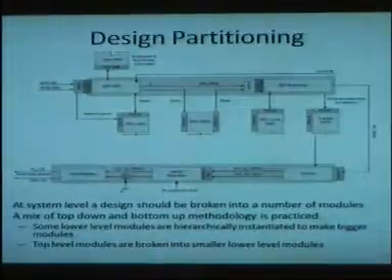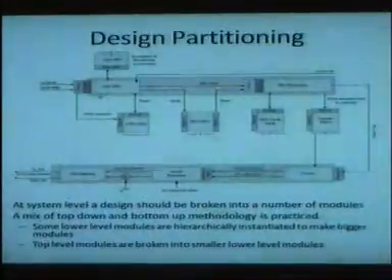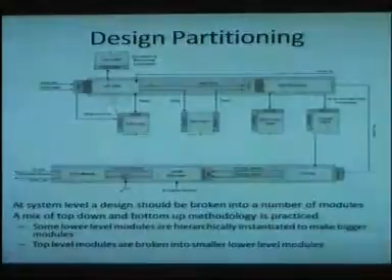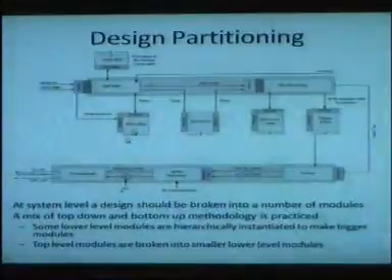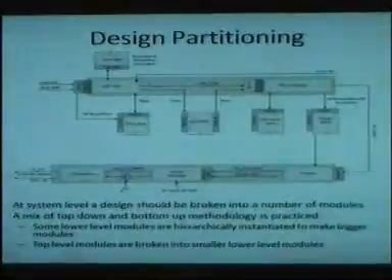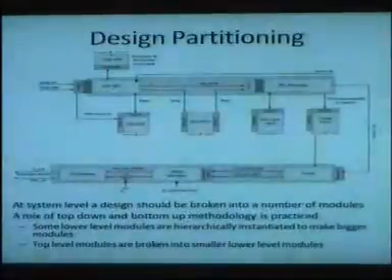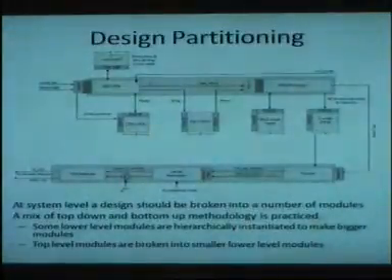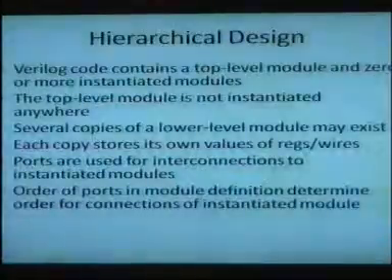Then inside a module you have smaller modules, and many of them. For example, this is an AES module. The AES module again has a few inputs and outputs, and you can see what inputs you have: an AES interface, and then this FIFO module. And you have many copies of this FIFO. So there may be modules where you have several copies, and there may be modules where you only have one copy, but each has its own character. AES has its own character. You never try to mix AES with FEC because they have different character, and that's how you design and test. So in Verilog, you need to think in terms of components.